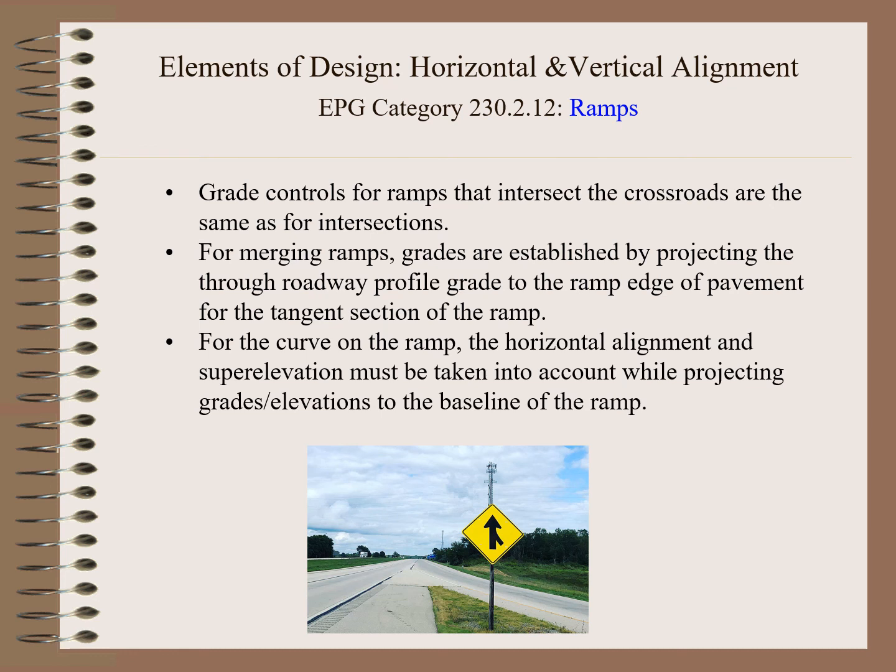For the curve on the ramp, the horizontal alignment and the superelevation must be taken into account while projecting grades and elevations to the baseline of the ramp. The picture on the next slide graphically shows this procedure.